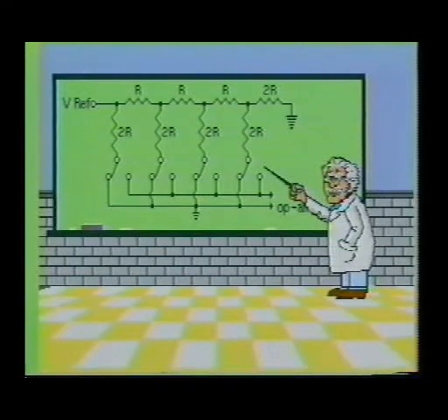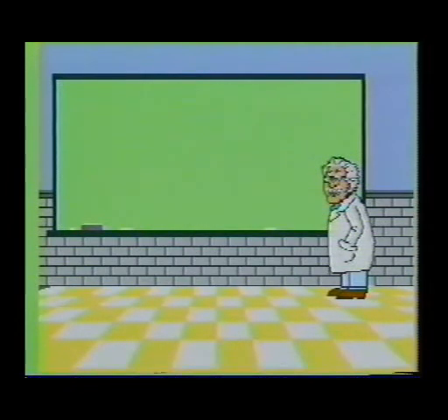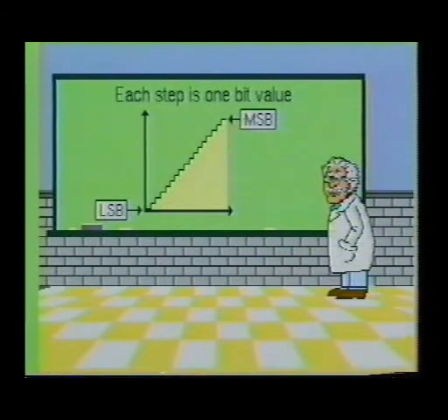The input resistors in the R2R ladder network consist of only two resistive values, the base resistive value and a value of twice the base value. The R2R ladder configuration is a much more precise digital to analog converter device since all the inputs carry comparable currents. Since the output of the DA converter is limited by the number of binary inputs, it cannot represent an infinite number of output levels. Instead, it produces an output which increases in steps according to the binary input.